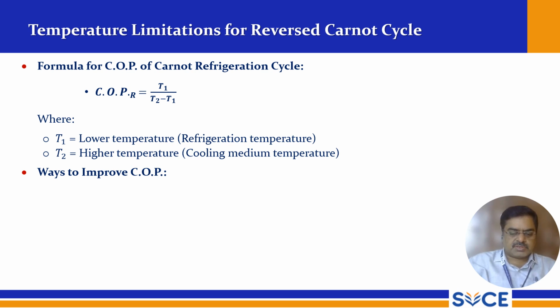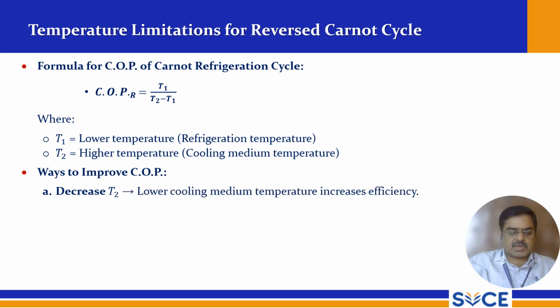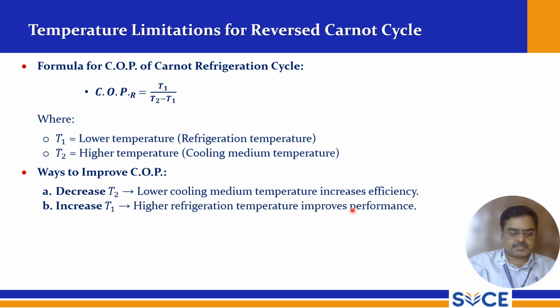We can improve the COP by decreasing T2, that is, lowering the cooling medium temperature increases the efficiency, or by increasing T1. Obviously T1 is in the numerator, so if you increase this, definitely the COP will increase. So a higher refrigeration temperature improves performance.